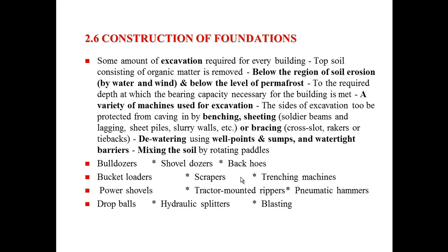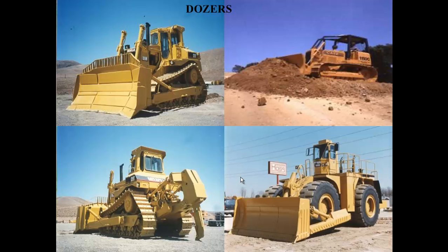In addition, we may be in an area where the soils are wet and maybe near a water source where we need to dewater the site. We may have well points, which are basically just drilled holes around the site, and pumps that allow us to keep water from entering the site while the construction is going on. And even afterwards, we don't always keep the well points in there, but we're certainly going to put some kind of a drainage system that's going to work well. But sometimes your water table just gets up above your foundation level and it makes it difficult to work, so you may have to dewater the site in order to make it work.